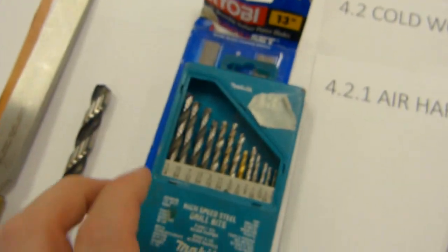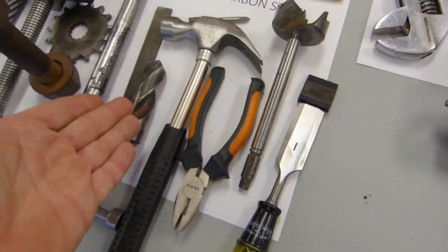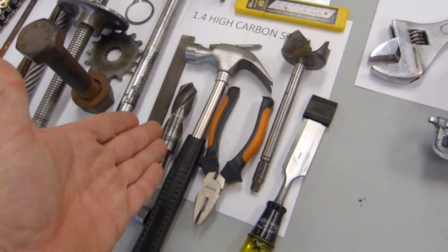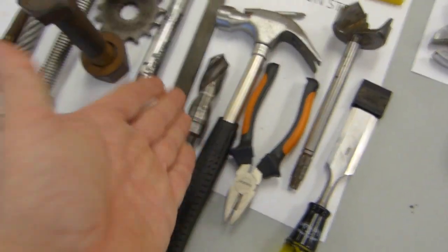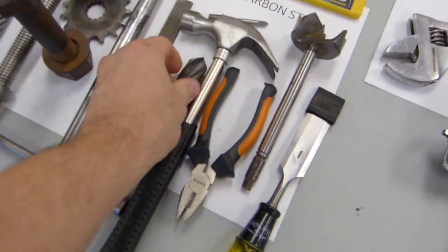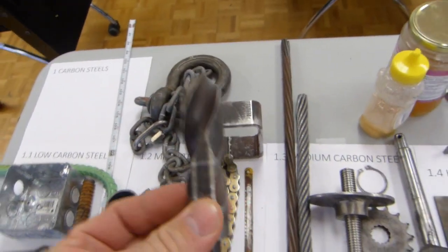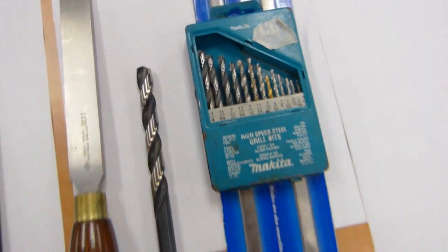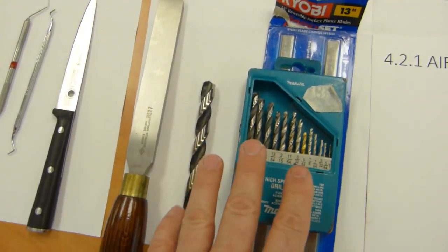If you go to the store and you look at high-speed drill bits and high-carbon drill bits, the high-carbon drill bits dull a lot faster than high-speed drill bits, because in the heat of work, whatever heat is generated, whether it's drilling into wood, copper, aluminum or mild steel, these still dull fairly fast, whereas high-speed steels don't. So that would be the idea of paying more for high-speed steels.